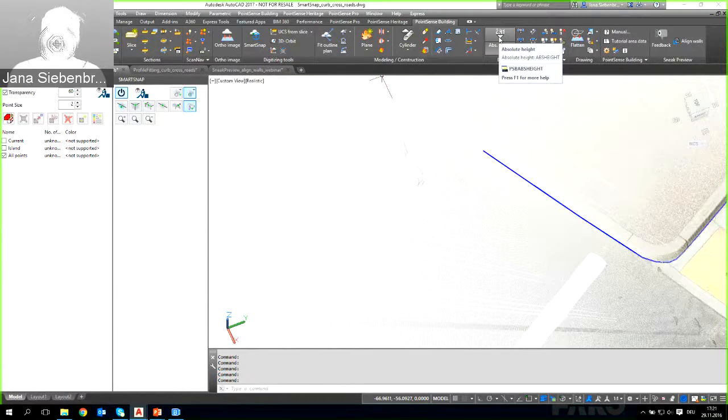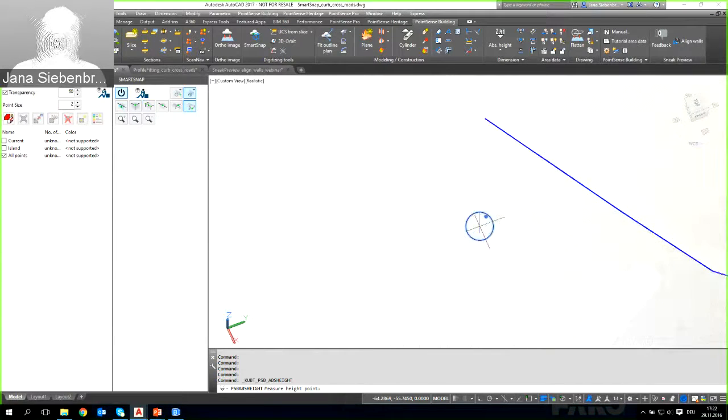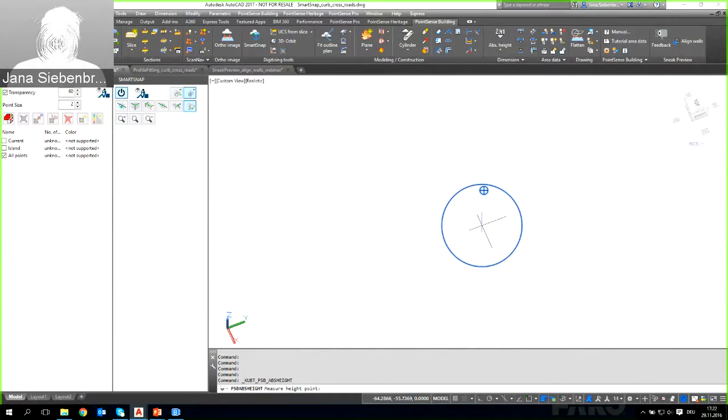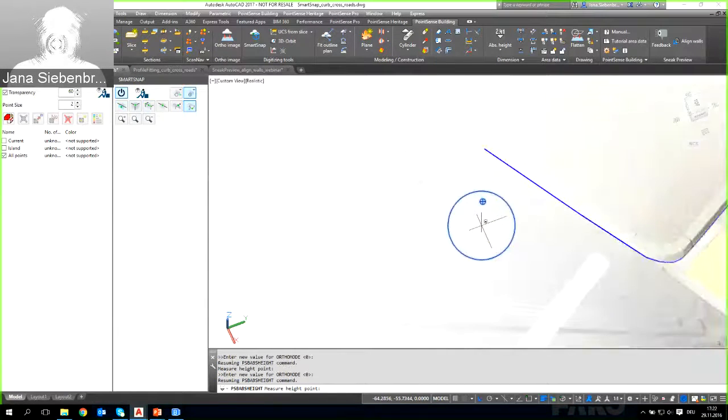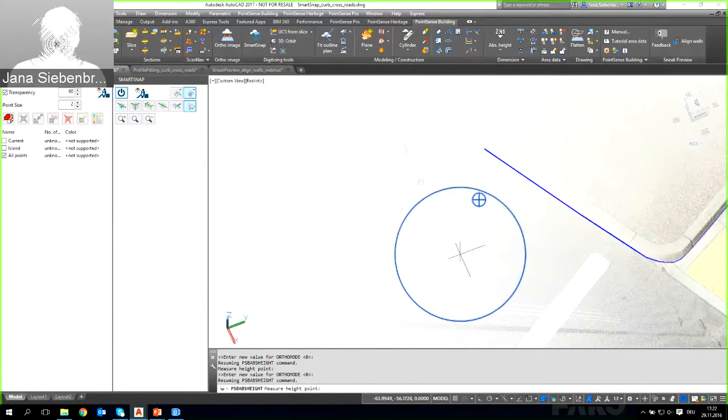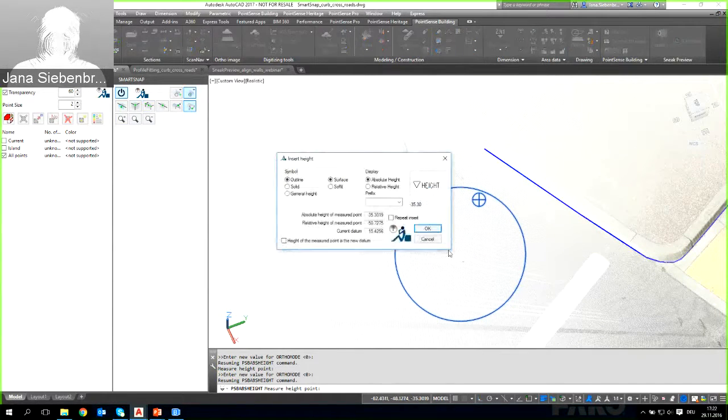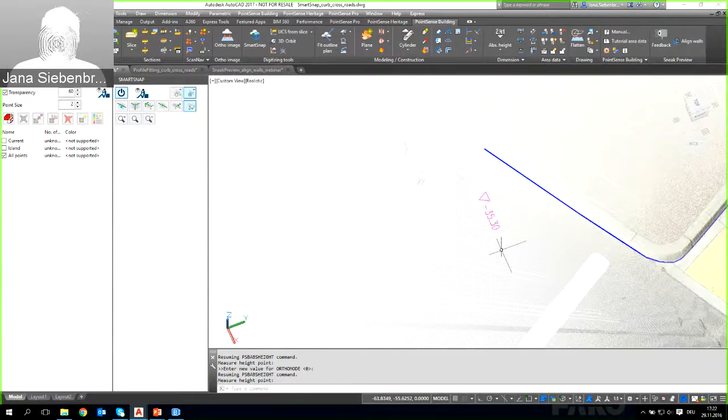the labeling tool for heights or elevations, and with the Smart Snap now the real lowest point enabled, you can see that the symbol changes a little bit. The small blue cross is directly inside the small blue circle, which means that you get the X and Y as well as the Z coordinate from the lowest point within that larger search radius. So if I want to analyze a larger area, I can enlarge the search radius, and my height annotation will be put to that snap point.